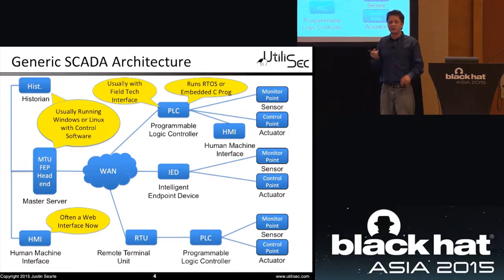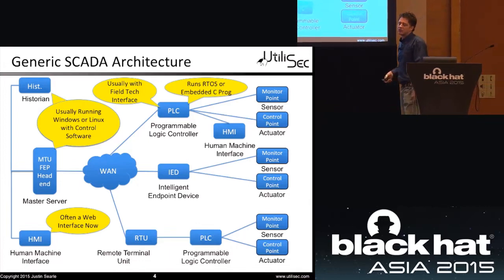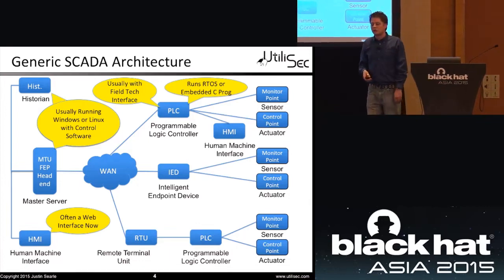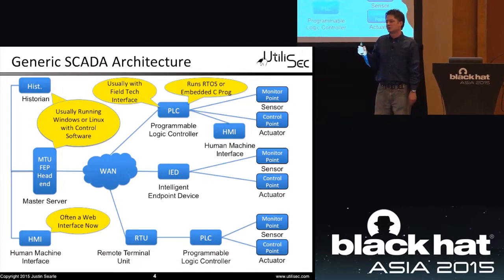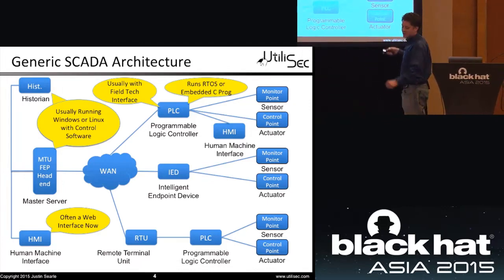It could literally be a file server that's sitting there. It could be an FTP server that's sitting there. It could be a big data server, like an Elasticsearch database or a NoSQL database. So a historian just means that we have something sitting there that's storing information about the processes. And they generally store what we call time series data. So information that we pulled from the processes, knowing, understanding of what changes we've made and what our sensors read from the processes.